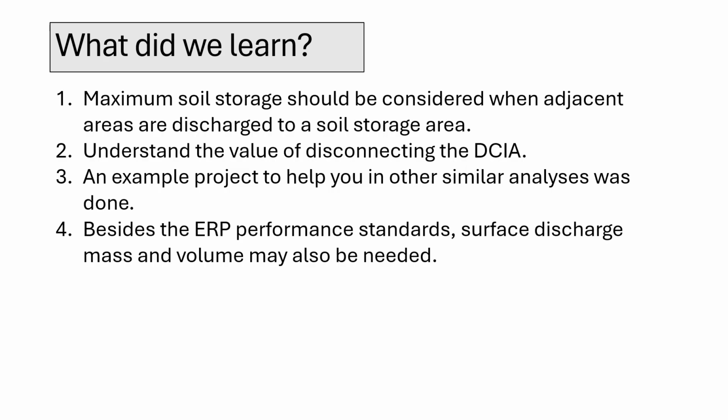For example, using a curve number of 50 and a 10-foot wide pervious strip, the runoff generated from a 32-foot wide impervious area can be fully stored within that pervious zone. We also covered the importance of accounting for maximum soil storage capacity, particularly when multiple adjacent areas are all draining to the same soil storage zone, since that storage can become exhausted quickly.